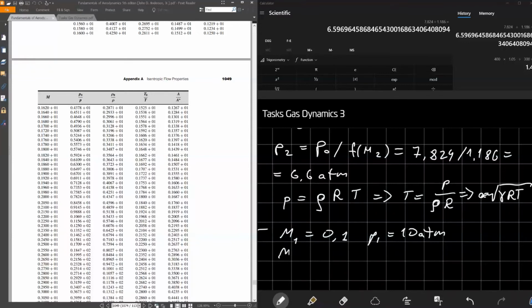The Mach number is very simple, right? We know that the characteristic Mach number is always equal to 1. But the characteristic pressure is a question. We use the appendix to calculate. Here is the same strategy as we used before in the previous task. So we first get the stagnation property.